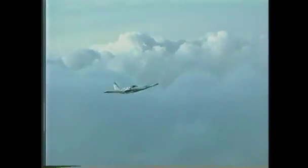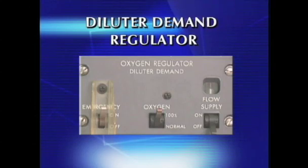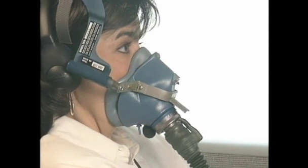The increase in the operational altitudes of aircraft dictated improvements in oxygen regulators. To increase efficiency and keep the body physiologically safe at higher altitudes, the diluter demand regulator was developed. Diluter demand regulators furnish oxygen when the user inhales.